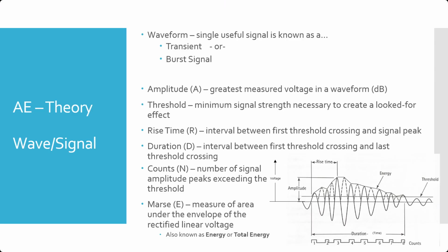The threshold is, remember, there's always some background noise, so we're going to set a point where, okay, anytime the amplitude is below this threshold, we're not really too worried about it. Right? We're primarily going to look at it when it exceeds a given threshold. And that has to be defined by a combination of material science and other experts in the field to figure out what that amplitude is. What constitutes a waveform? What constitutes a signal versus just the normal noise you would expect out of a given object? And so that sets our threshold.